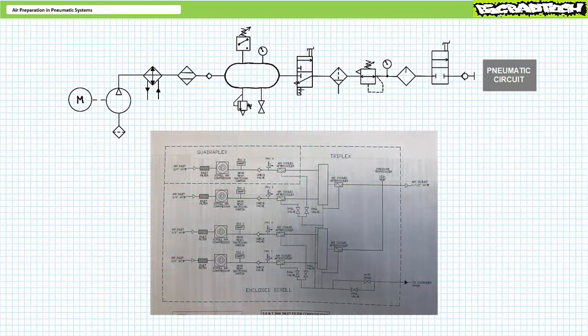Case in point, consider this quadruplex compressor circuit in a soundproof enclosure consisting of not one, but rather 4 separate scroll-style compressors hooked in parallel, driven not by a constant speed motor, but by 4 variable frequency motor drives. In the event a little air is needed, a single compressor can be driven at a low speed. If, however, demand increases, all 4 compressors can be run at top speed to meet the demand. Compressors can additionally rotate duty cycle.